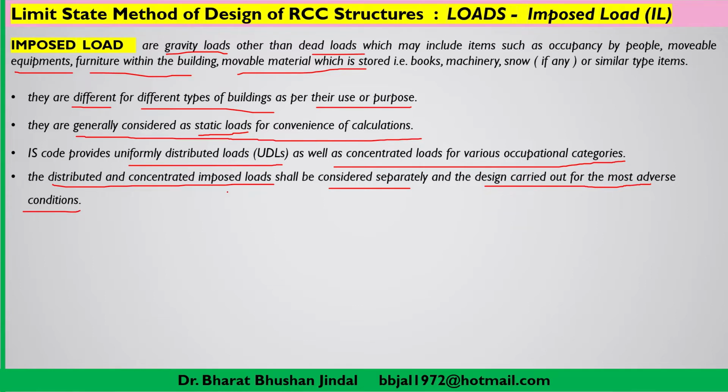Here you will come across the term combination of load later on. That means when you are going to design a structure, you have to take the combination of load and follow that combination which is going to offer the most adverse condition, so that our structure is designed for the adverse possible conditions which may happen during its lifetime.